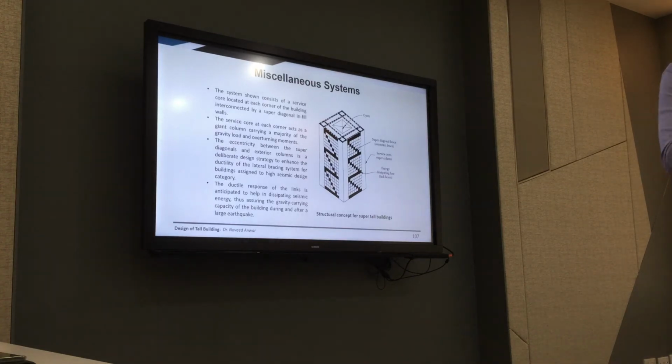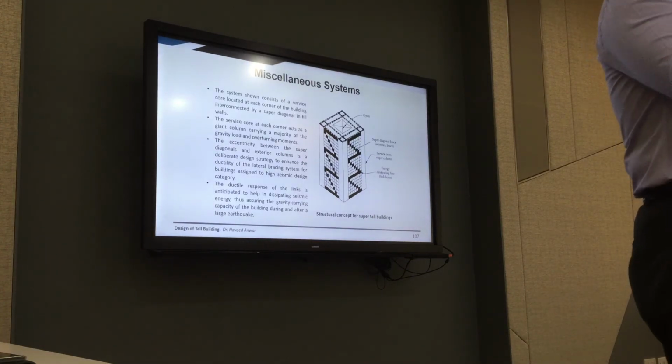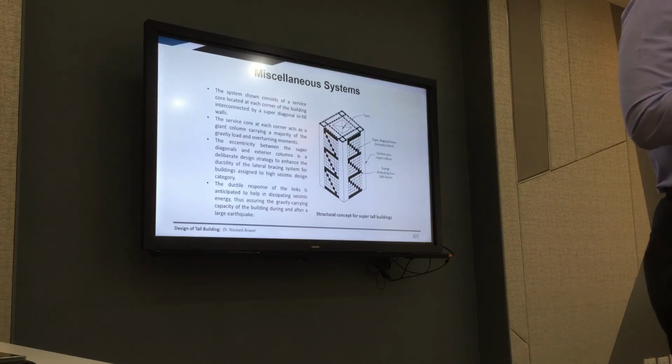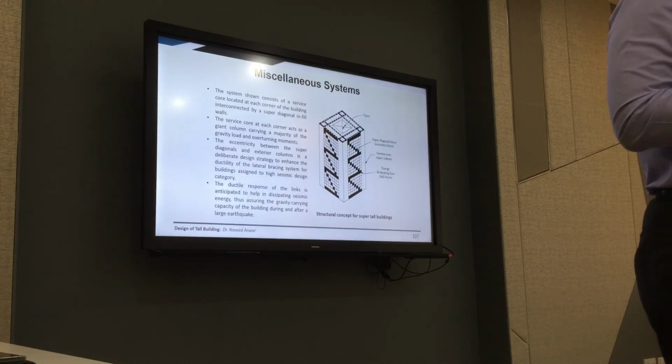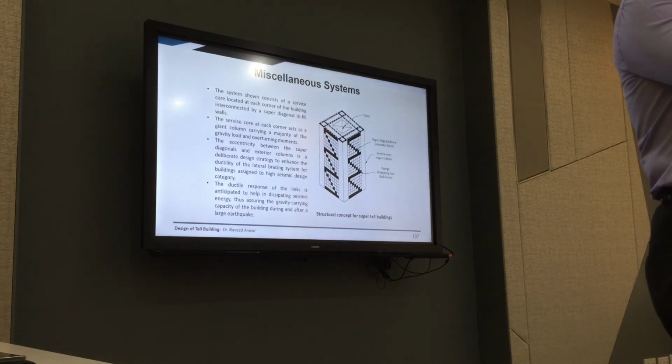So same one. That's why I say everybody is going to say that. Okay. This is about the concept of strong shear connection, shear wall and outrigger. I learned how frames and shear walls can be used in the same building and they help to reduce the deflection at the same time. Deflections and also bending moments.